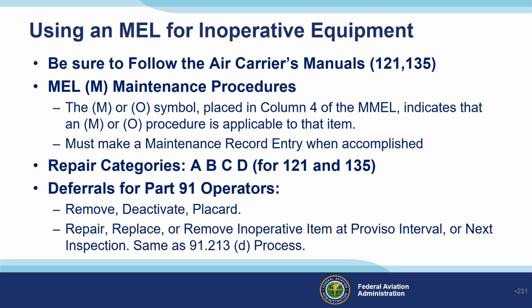Otherwise, a Part 91 operator using an MEL will just remove, deactivate, and placard the equipment. It's just the same as the 91.213D process.